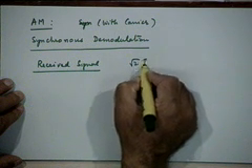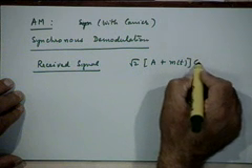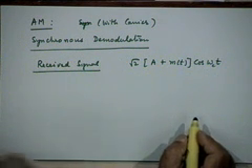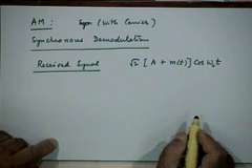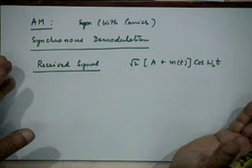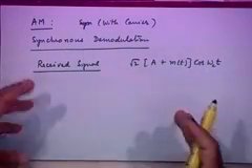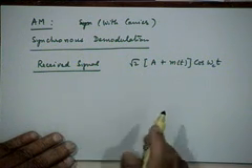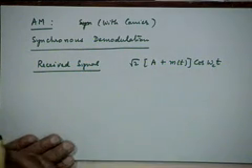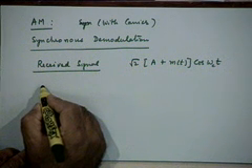You can say root 2, there is a carrier component and there is a modulated message component. Alright. So, this is a transmitted signal, AM signal with carrier. The factor of root 2 or factor of 2 that I might include is just to make sure that the final SNR, the message power part, is the same. There is no other requirement. So, what is the received message power in this case?